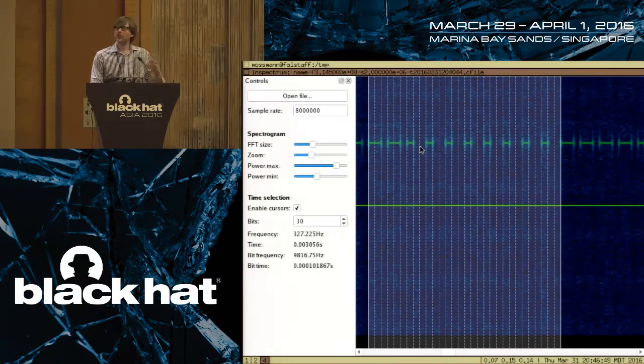So I'm going to call this 1/3 of a pulse period, this 1/3 time unit, a symbol. And I'll just say that if I were to read this as symbols, and say that an on is a 1 and an off is a 0, then this section that I have highlighted here I would read as 110, that's a long pulse, 110, that's a long pulse, 100, that's a short pulse, and so forth. So I have this string of symbols: 110, 110, 100, 100, 100, 100, 100.